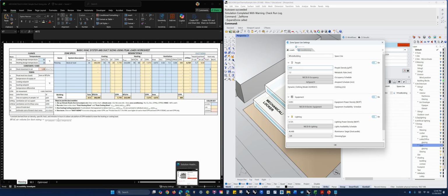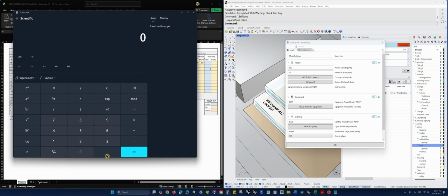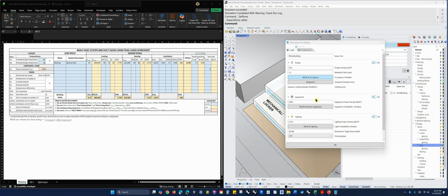In our code in the U.S. and the IBC, this is from the egress occupancy, in square feet per person. So if we divide the 1 by 0.02, we get 50. That's 50 square feet per person. If you look up the egress occupancy, that's typical for assembly. So this makes sense.